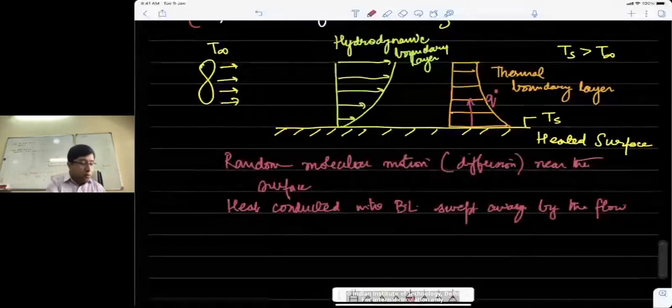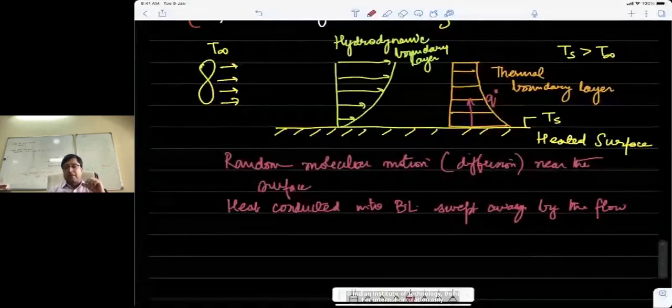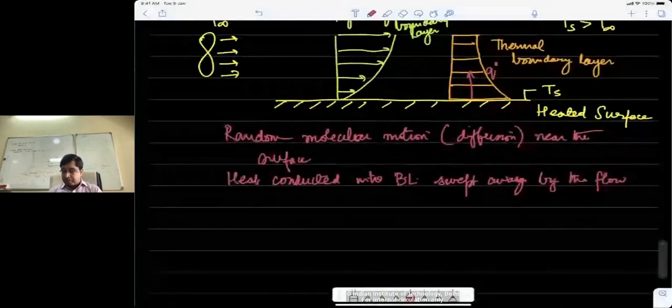So in most of these convection type analyses, it becomes important to understand how boundary layers form on the surface, both hydrodynamic and thermal boundary layers. So when we talk about convection at some point in this course in more detail, we will actually do bottom up analysis, where we will first understand these boundary layers and their role in letting us calculate how much heat transfer we should expect from a convection mode.